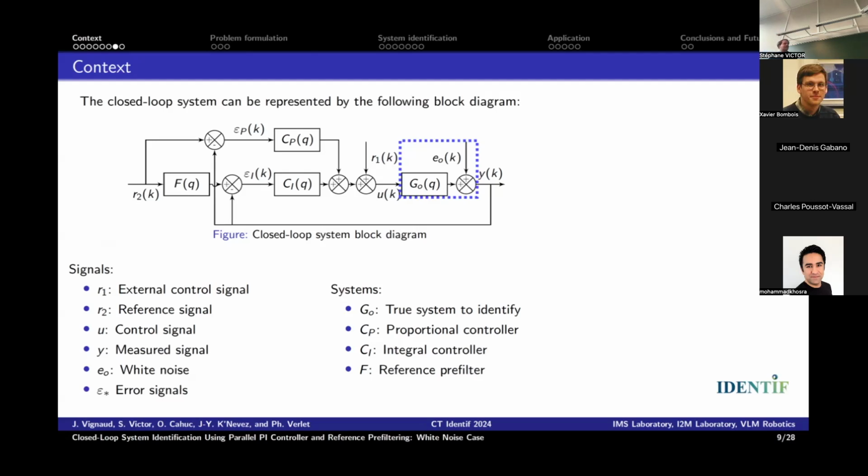That's the prediction error you will minimize, whose power you will minimize, is y minus G(theta) u. Okay. And there you know that you will be consistent. Well, of course, you have to initialize with a good theta zero, but it's a nonlinear optimization. But you know you are consistent, and that will be the minimal variance estimate.